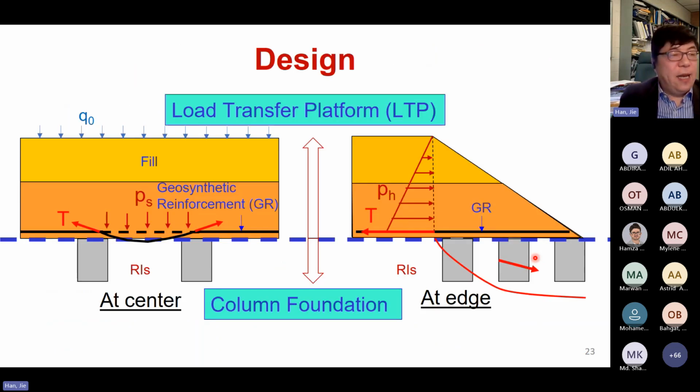Okay, regarding design, there are 2 things we need to consider. One is at the center of the embankment, and the other is at the edge. So the designs are very different. Within the center, typically we're dealing with only vertical load. But at the edge, we're mostly dealing with lateral loads, okay, and the stability issue.